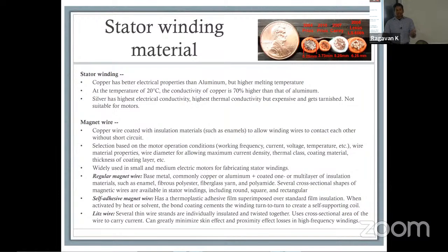Heat. So the question really is, how hot are you going to get? When you put more copper into it, the question is, is your thermal system robust enough to extract the heat? If you're trying to do forced convection with air flowing through it, and you have a packed winding slot, it's a problem, right? On the other hand, if you have something that actually extracts the heat, like a heat pipe, or you have epoxy or something like potting that allows you to extract the heat directly, take it to the lamination and outside into the fins.